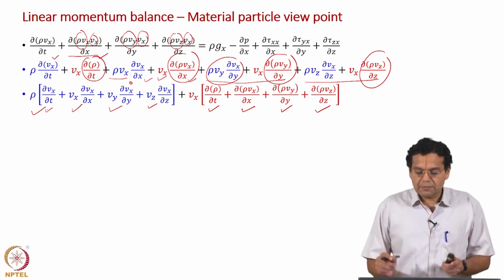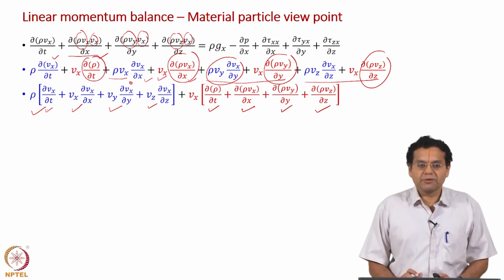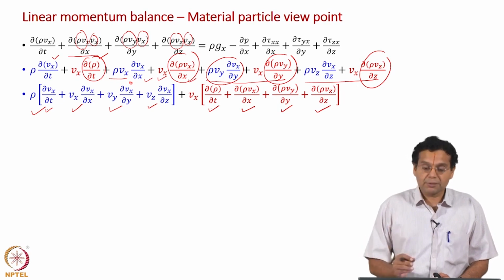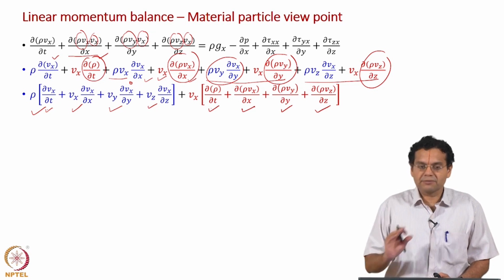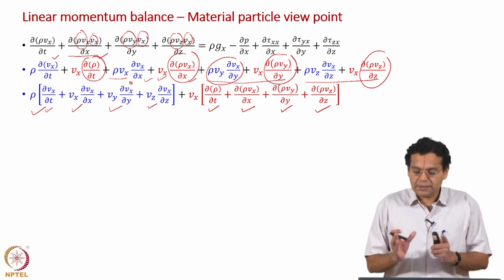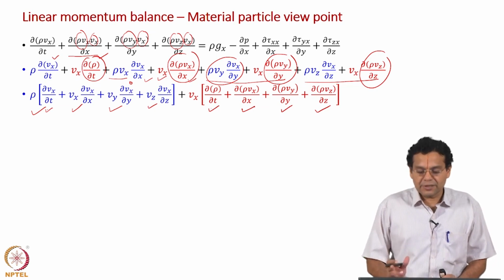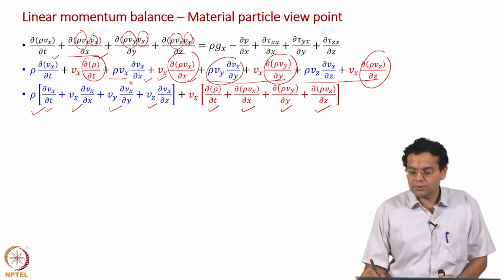Now the terms in the bracket of the red color term is the equation of continuity, we know that goes to 0 both for compressible flow and incompressible flow. Okay, no assumptions here. So, the second term just vanishes, the terms inside the square bracket is nothing but the continuity equation or the differential mass balance is equal to 0.